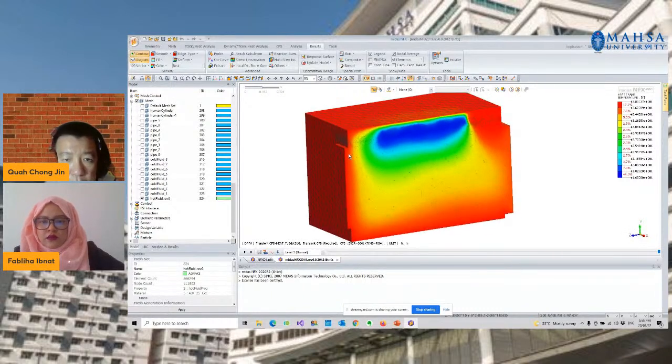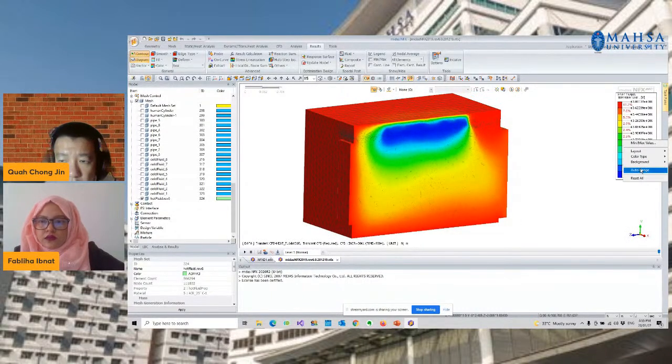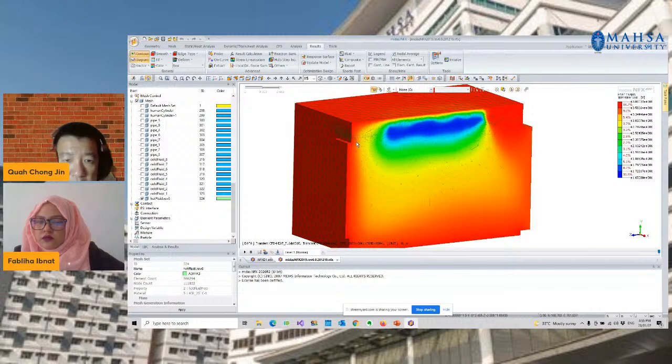And you should be able to notice how the temperature is distributed. You can see that the cold air is coming from the top. The hot air is reaching about 38 degrees Celsius. The cold air is about 16 degrees Celsius. So how the cold air is supposed to cool down the environment effectively, from the point of view of natural heat convection in this case.